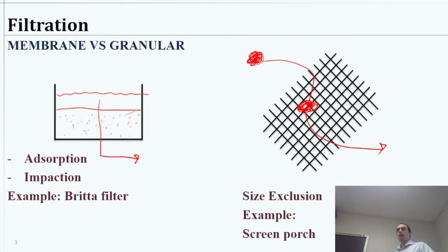So it's activated carbon. Activated carbon has a lot of surface area, and organic chemicals like to stick to that much more than they like to hang out in water. So water is very polar. This activated carbon is not very polar, so it's very attractive to non-polar stuff.